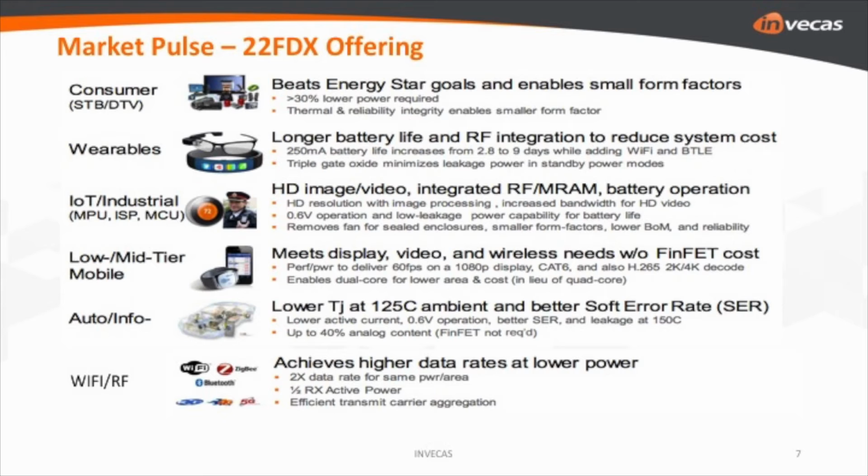That enables a lot of product designers to design better, more efficient and cheaper products. On the auto and infotainment side as well, this is one of the processes which could do very well, mainly because of the low active current, the 0.6 operations, and better leakage profile at temperatures as high as 150 degrees centigrade, and simply because up to 40% of analog content, and FinFET is not required at all. So that's why auto and infotainment is going to be a very key market when it comes to 22FDX platforms